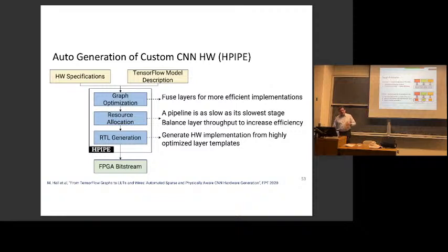So it takes a large number of clock cycles to go through all of that input. Some of these layers have more work to do than others. So I showed you that some of those convolutions in that example network were 7 by 7 kernels. So that's like 49 multiplies and 48 accumulates to produce one output. Some of them were 3 by 3. That's 9 multiplies and 8 additions to compute an output.